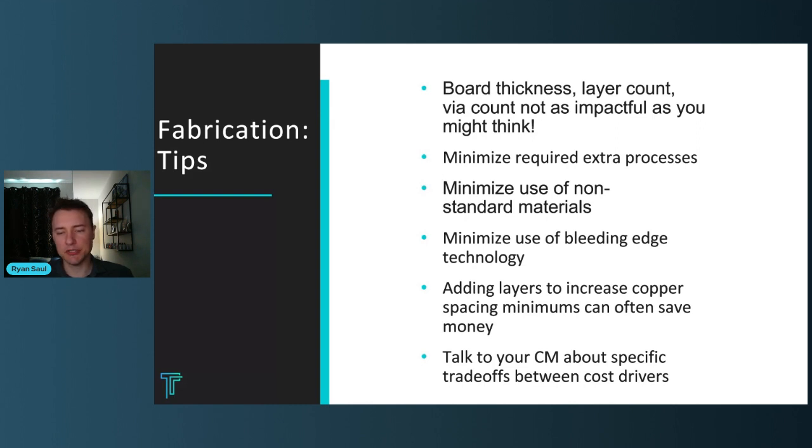But it's not just do they have that material, it's do they have that material in the thicknesses that would be required to complete your design, with the copper weights that are attached to your design. So it could be that they have that material, but they don't have that material with 2-ounce copper, or they don't have that material with the core thickness that's required to meet your impedance targets. So allowing the fabricator flexibility to make small modifications to the dielectric is critical.